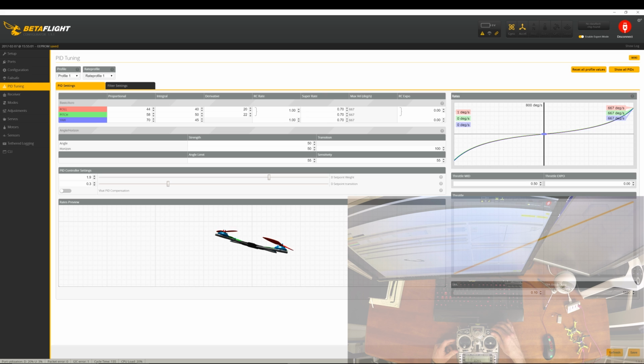So that's the I term of PID, the middle position for the switch, and we're going to increase that and leave it up for a couple seconds. You'll see this blue light is kind of flickering. That means that the value is being added to. We'll bring this back to its neutral position, click refresh, and see 5363. So the I value has increased.